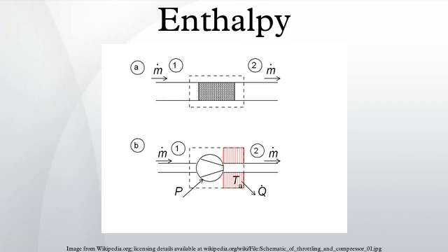In the first law for open systems, applied to the system in Fig 3a, all terms are zero except the terms for the enthalpy flow. Hence, since the mass flow is constant, the specific enthalpies at the two sides of the flow resistance are the same. That is, the enthalpy per unit mass does not change during the throttling. The consequences of this relation can be demonstrated using Fig 2.